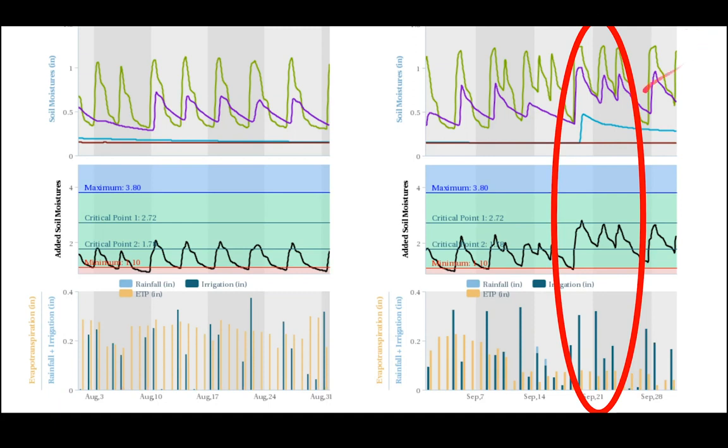That first event, he went out with the concept of, I'm going to run 48 hours. And I told him, well, that doesn't do anything, because you're irrigating that third and fourth foot where you have no roots. So you're just wasting water. What you want to do is run more frequently. And that's what he did. So he got more water out there, and we got a very good size without affecting the dry content on the olives, and that was good news.